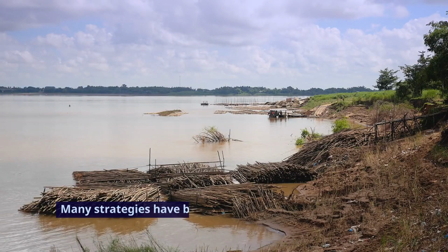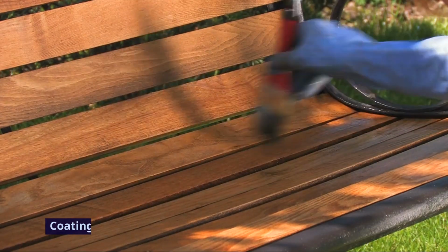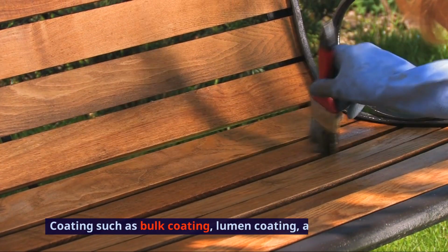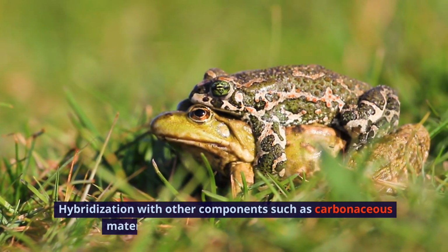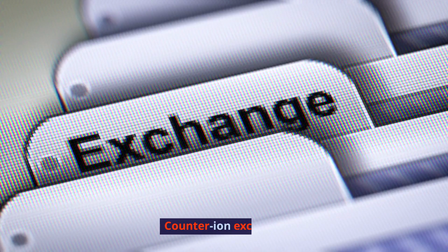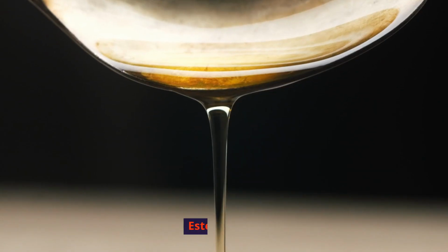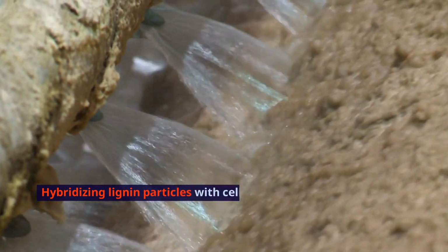Many strategies have been developed to improve the water stability of wood-based structures, including coating such as bulk coating, lumen coating, and fiber coating, hybridization with other components such as carbonaceous materials, polymers, minerals, and metals, acetylation treatment, counter-ion exchange, cross-linking treatment, esterification, furfurylation. Some specific examples of these strategies are hybridizing lignin particles with cellulose paper to form a